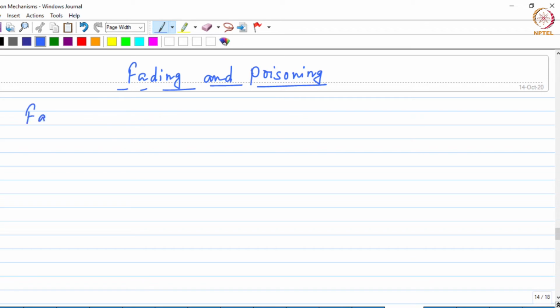This essentially means the nucleating surface that you had is either lost or poisoned, and it has lost its grain refinement ability. So we have seen that the solubility of titanium in aluminium can go up to 0.25%.